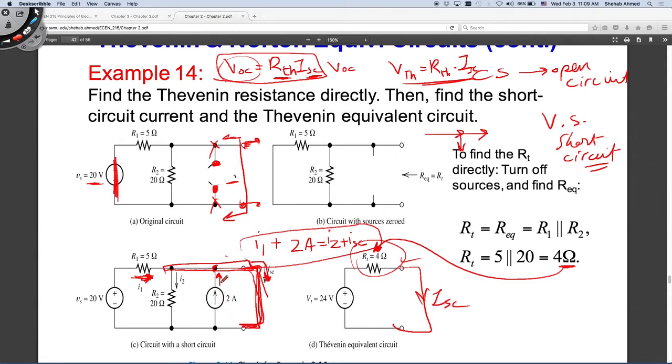Because here I have no control. This is a constant flow rate pump. It will always push water through. It will always be pushing. It will never take in any of the current. The current will not flip the polarity in this branch. The polarity of current in this branch is 2 amps. It is dictated by this constant flow rate pump, right? So that means that I2 is what? I2 is the current here. What is I2? It's 0. So I2 will be 0.